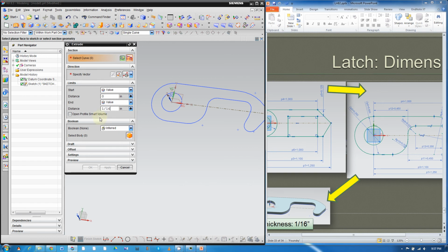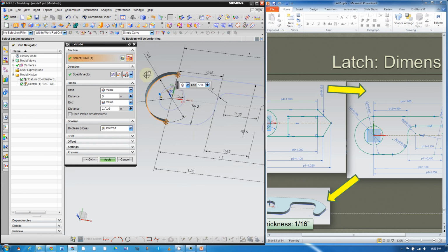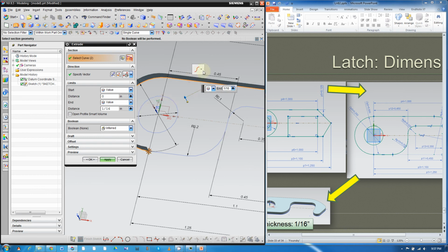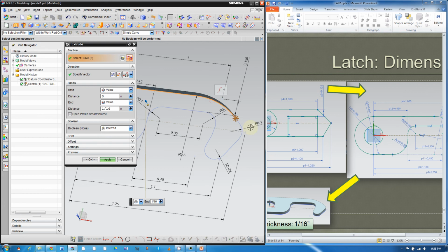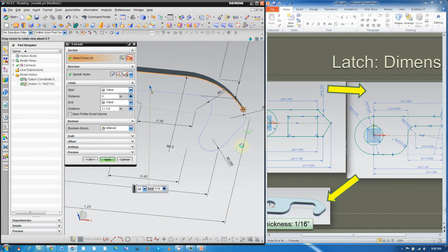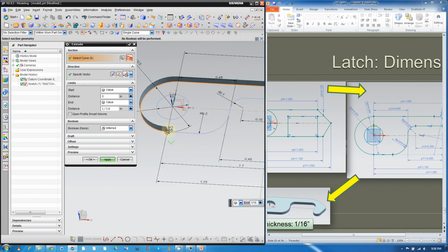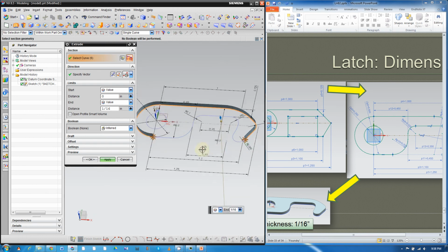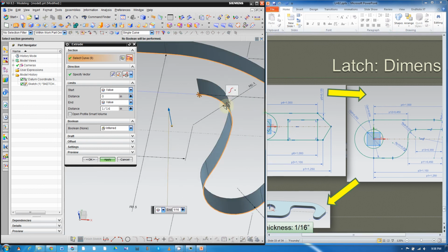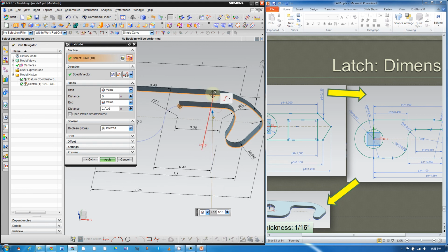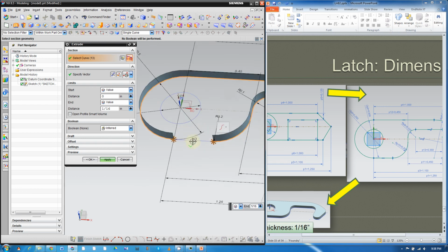As you can see, if we continue to pick the curves, the extrude will grow as we pick, and the open end will always have one big star. If there's a star between the two sheets, that means there's a tiny opening, which is not good for you. Pretty much this outside curve is fine. Now we can pick the arc, then everything's good.